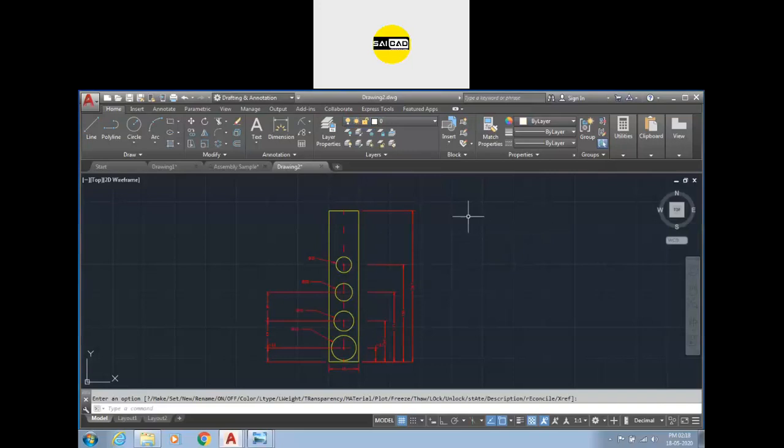Okay, so layers will be used to select the objects very easily or to clean the drawing, because sometimes you don't want to see the dimension, sometimes you don't want to see the reference. In that case, it will be very helpful. So always create layers, work with the layers.